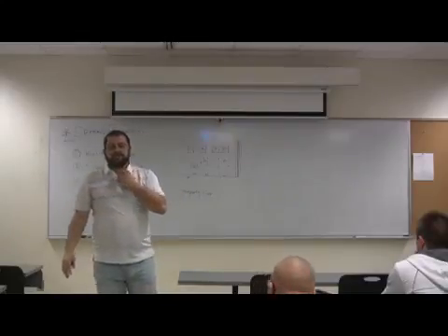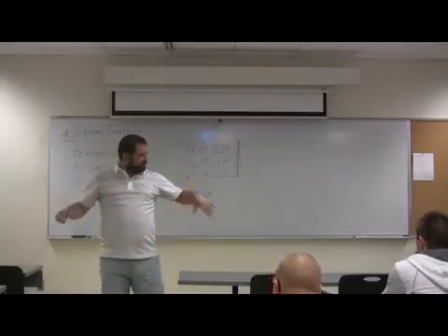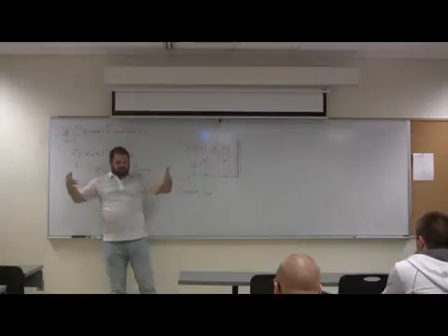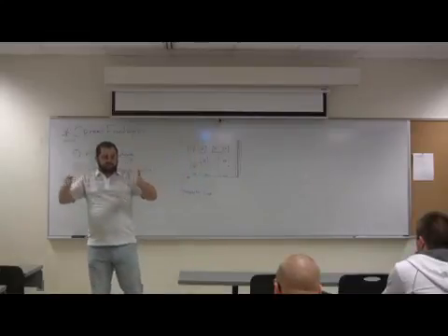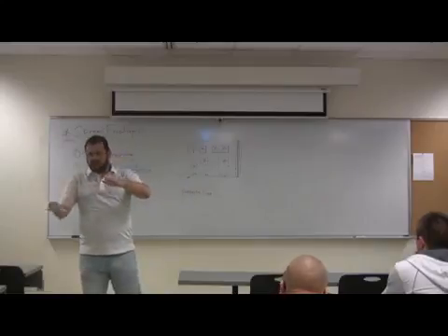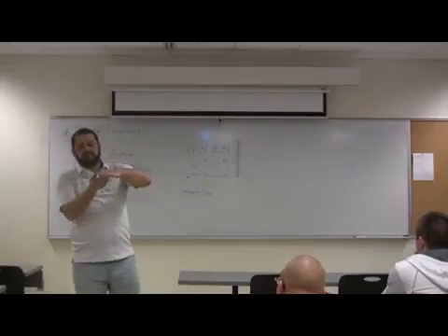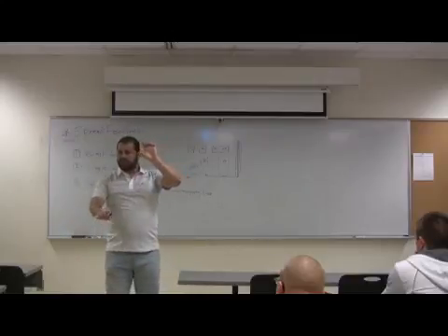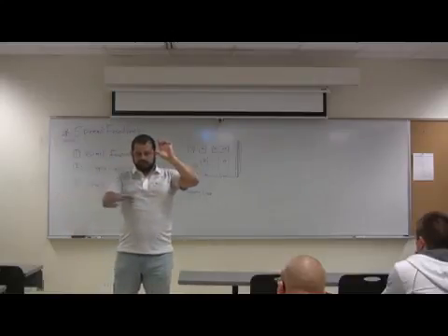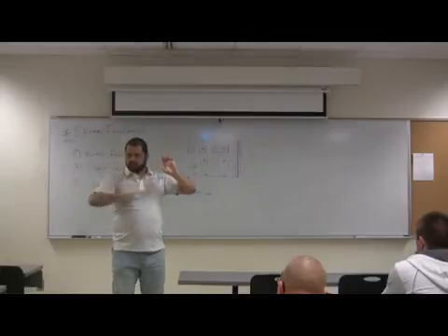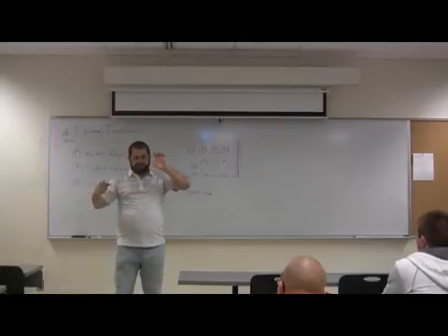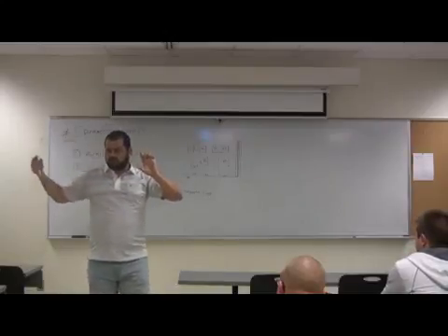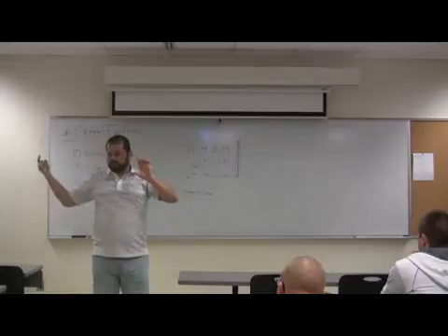In any building, once you build your footing here, usually we tie the footings together so that we have an integral foundation at the top. Once you reach the first floor level in the United States and many other countries, they have a small 4-inch slab on grade at the first floor level. It ties all the columns together, and this 4-inch slab is very powerful and strong in resisting any lateral load or earthquake loading.